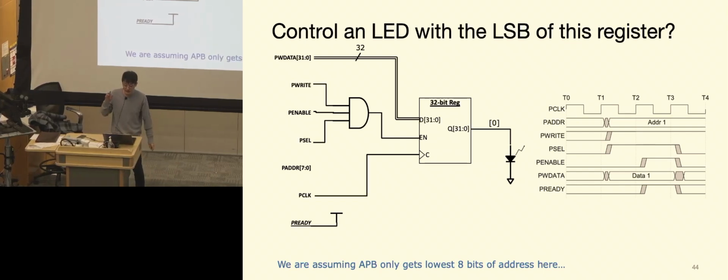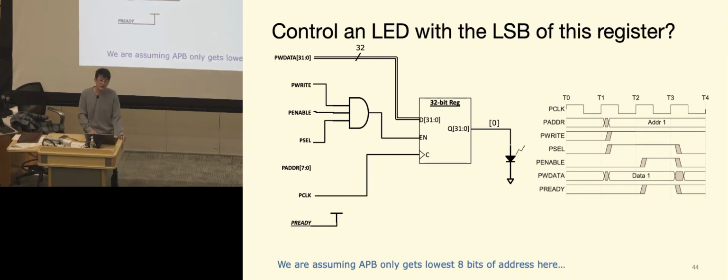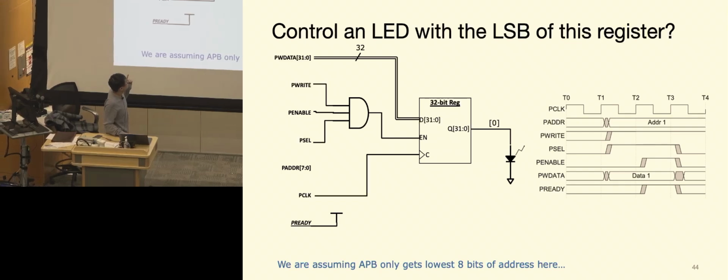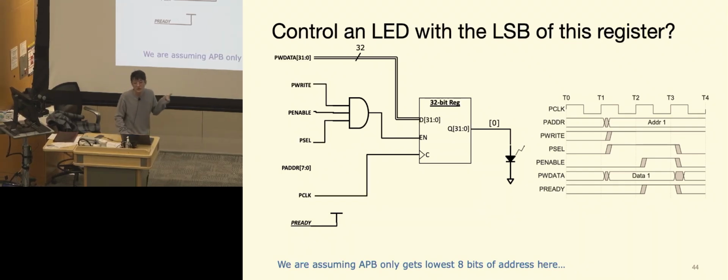Pretty much, it's an output from the slave to the master; the other ones are from the master to slave, essentially. Why is this always ready, but the previous one is only ready at a certain time? For this one specifically, we were trying to update as soon as possible. The previous ones, I think it should be okay to have the ready on earlier, but because it's a store, we want to make sure all the data and all the other instructions are ready there. And then it turns on the ready.